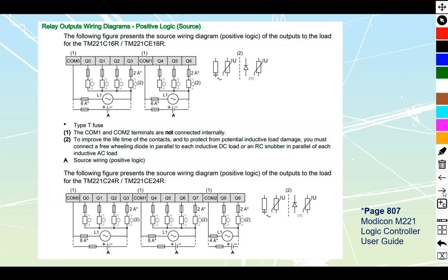And we can also, if we're using relays, go with a sourcing type, which is where we're going to have a positive that's going to be attached to my commons. Once again, we are going to deal with all of these as individual small fast videos later on.